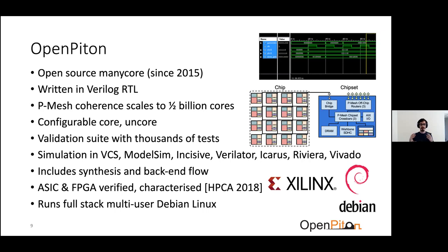And one of the big things is, right, this was designed to be an open source research platform where people can change the sizes of things, particularly architects, right? So they want to change a bunch of different configuration parameters and test out their research widget according to the design space that's available to them. And so we provide a lot of configurability there, but then we also provide a validation suite. So you can test if you go in and modify the coherent system in some way to add some capability, that you didn't actually break the rest of the coherent system in the process.